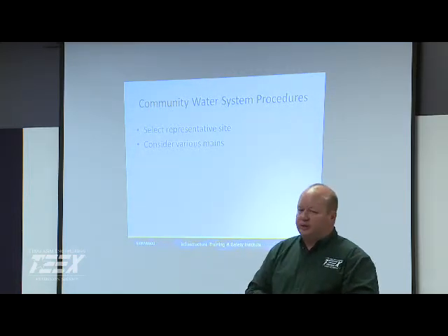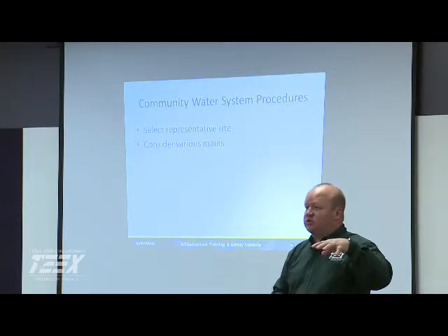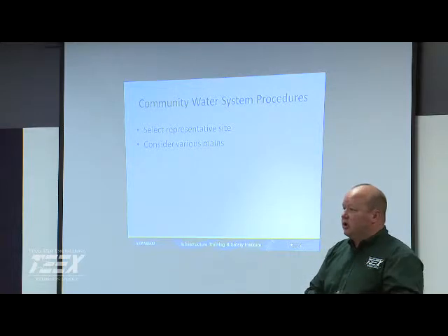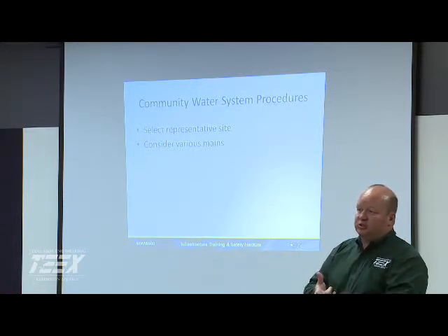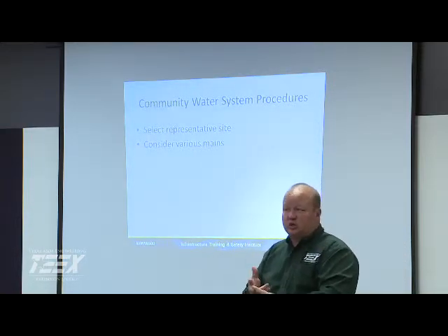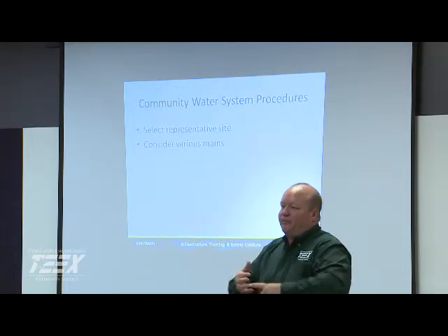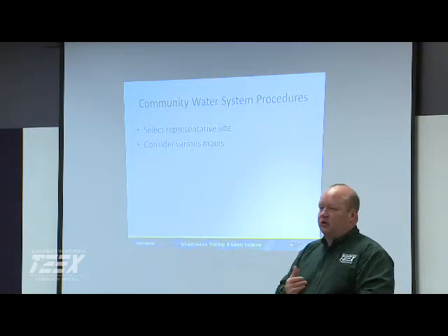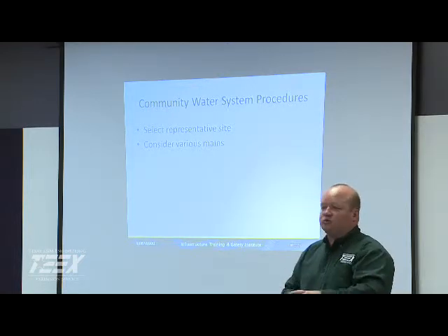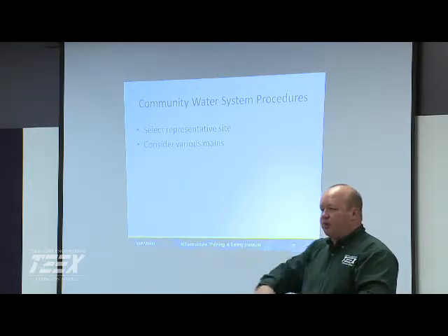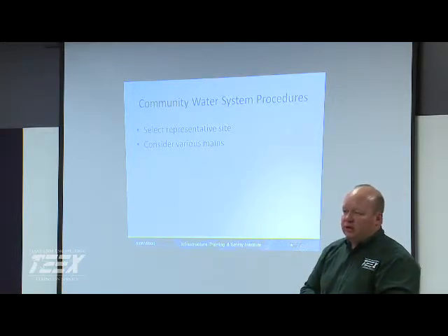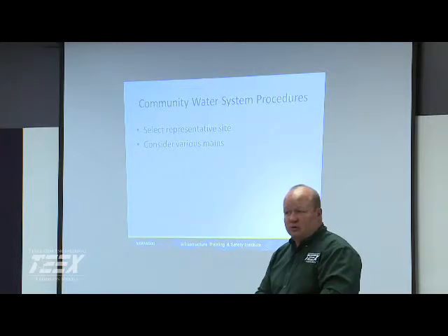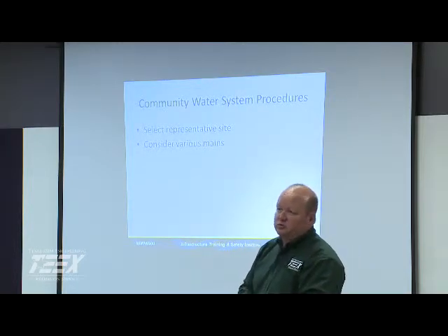One of the things that they have are truck mounted units, and that takes just one person. And it's an investment on the front side, but I think in the long run it saves you because your valves work, they're getting exercised properly, and it doesn't take a lot of manpower to get out there and actually operate your valves through the system. And if you have it set up on a regular program, you know what your valve position should be, and it can be real beneficial.